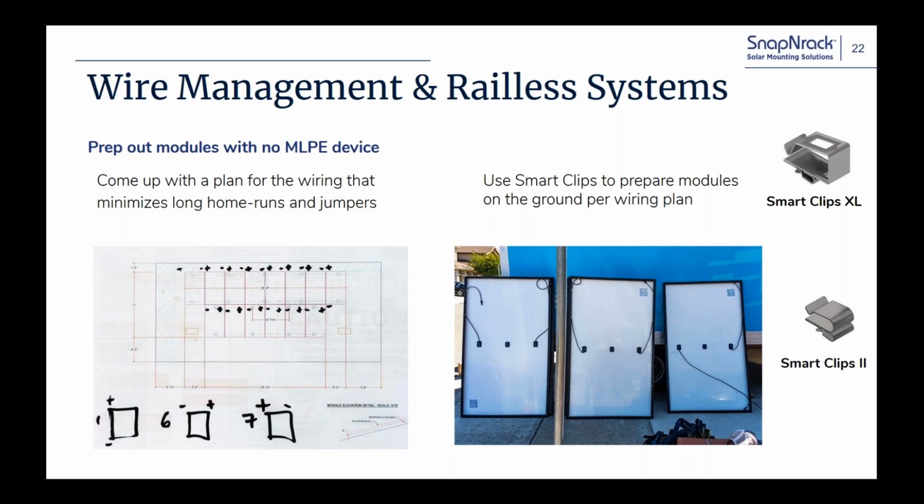And they created a couple stacks of modules. When they're installing that first row, they'll call for a negative on the right or negative on the left module, depending on which module they're installing. In this case, all of the negatives are going to be on the left-hand side for this entire row. And then they'll have the one transition module at the end. That's this module on the far right, that one stack, that has a positive at the top and negative at the bottom, and then they can just clip those two together, and then they install the next row.